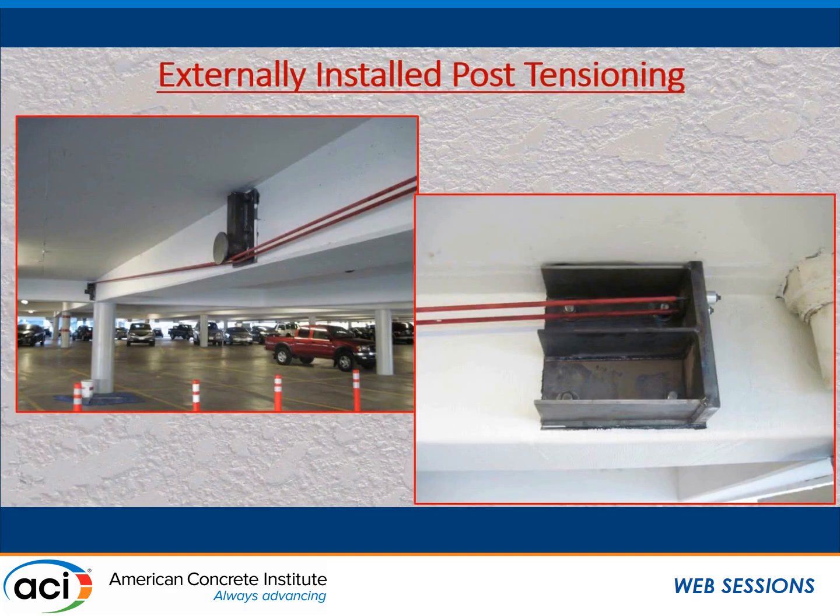So at this point, I'm intimidated because Gene's photos of external post-tensioning were 100 times better than mine, but this is a cool solution to a project. I worked on a job in San Diego years ago where they put in just a small amount of external PT in precast, and it put the camber back in and solved this problem, and it moved that deck just enough that the cracks closed up and everything was great. We've done a few jobs with it, but not to the magnitude that Gene was showing, but it's a wonderful solution to the right situation.